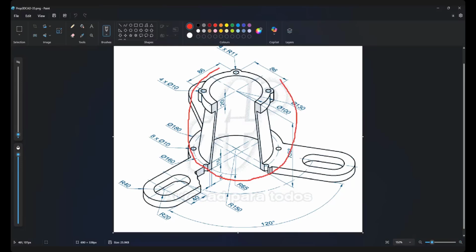For this cylindrical shape, like I've shown you previously, this is not a bounding box modeling approach. Similar to the one I've shown you, it is a base profile approach. First we do it part by part. We have 2 parts. First is the cylindrical shape at the center. We need to draw this profile. It's kind of like a revolve around a center line in the middle here, right? At the center, we have a center line.